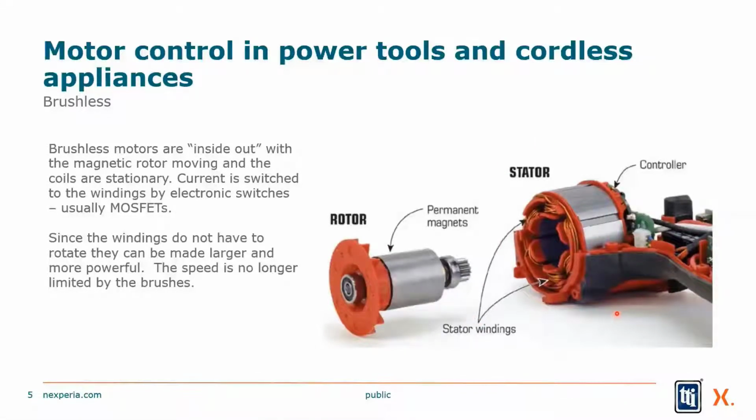Well, what does that mean? First, I don't have brushes on it, so I'm not limited by the mechanical switching speed of the brushes. The arcing and the wearing out and the carbon dusting and everything that happens with those, they're gone. Also, I don't have all those wires spinning around, so I can spin a solid chunk of magnetic material really fast. So I can get a lot of speed out of this. It's not going to arc. It's way more efficient. Per pound, I can get way more power out of one of these motors than I could the original electromagnet spinning type motors, the brush motors.